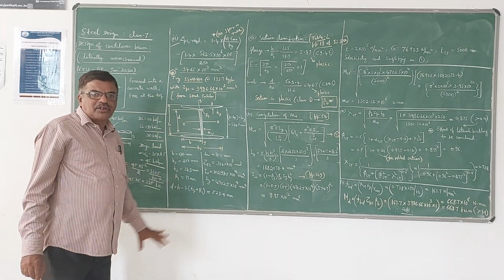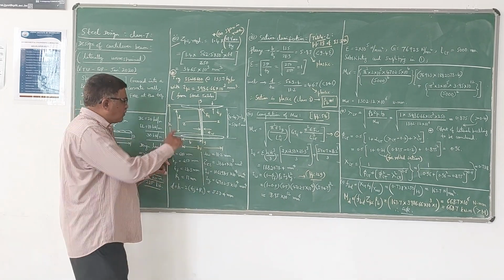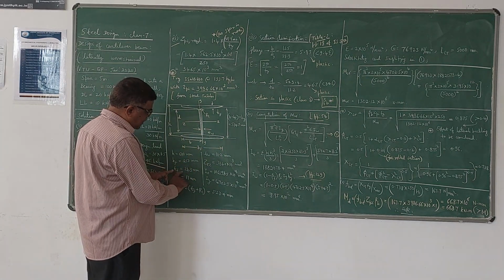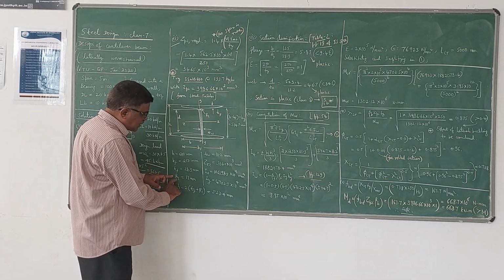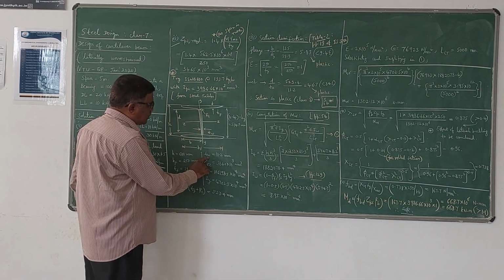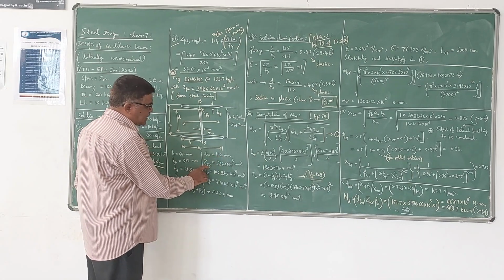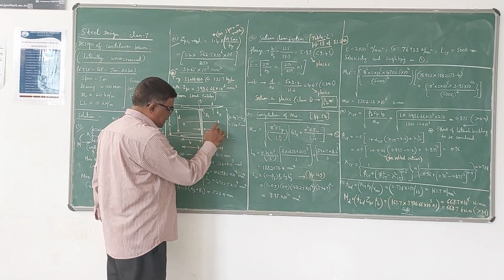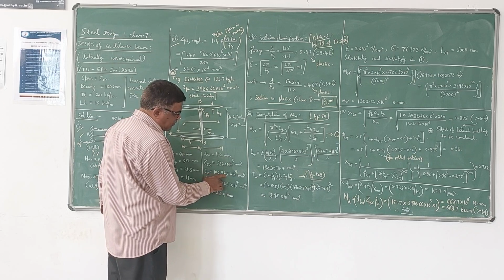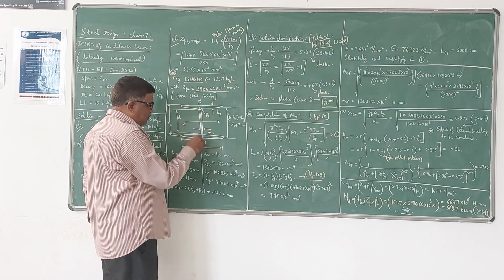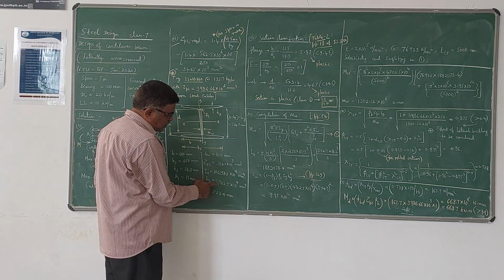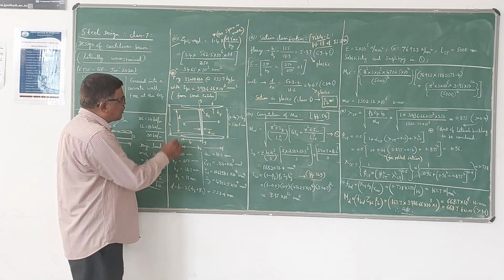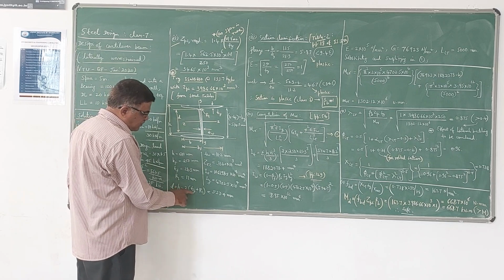Now these are the geometrical dimensions of that particular section. The total overall depth is 600 mm, width of flange is 250 mm, TF the thickness of flange is 21.3 mm, radius R1 is 17 mm, TW thickness of web is 11.2 mm, ZEZ the elastic section modulus is 3340 into 10 power 3 mm cube, IZ moment of inertia about the Z axis is 106198.5 into 10 power 4 mm 4, IY is moment of inertia about the vertical Y axis, 4702.5 into 10 power 4 mm 4, and D is the depth of web, which is given by H minus 2 times TF plus R1.